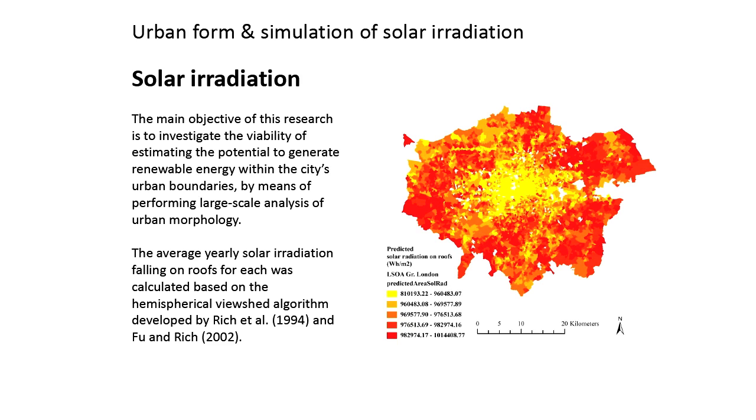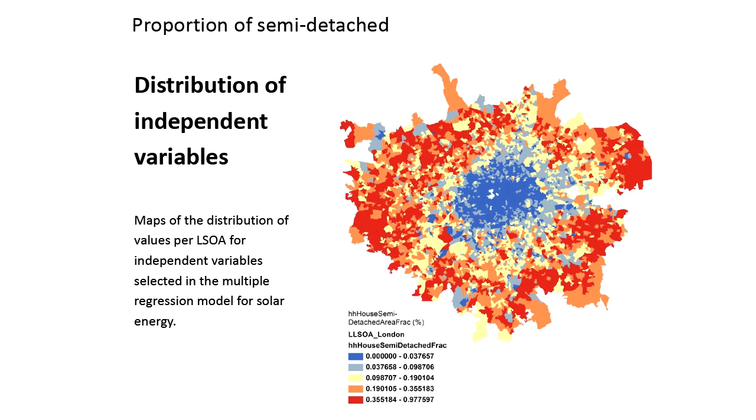And then we wanted to compare that, and I'll do this very quickly because there are other people who've done this kind of analysis before, to the solar potential of the urban environment. If you look at London, you can see that in the center of London, the solar potential is much lower than in the rural environments. So solar energy is particularly suitable for more suburban developments, where the demand is also a little bit lower and more spread than the concentrated city. So you'll never meet your demand with solar energy if you try to do it by putting PV on city center buildings.